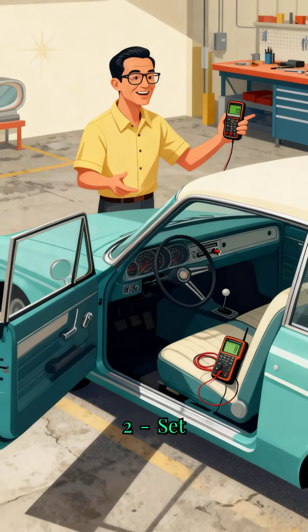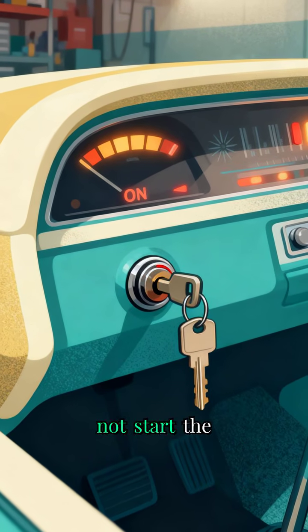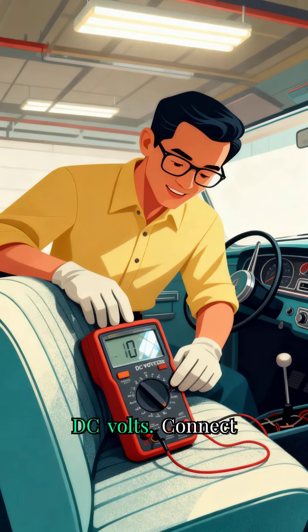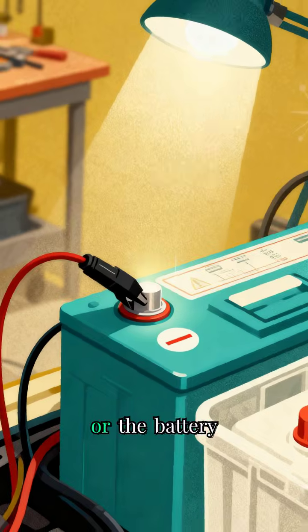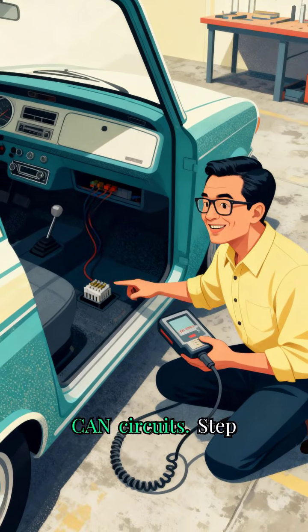Step 2. Set up your multimeter. Turn the ignition on, but do not start the engine. Set your digital multimeter to DC volts. Connect the black lead to a known good chassis ground, or the battery negative terminal. Now, begin testing the CAN circuits.